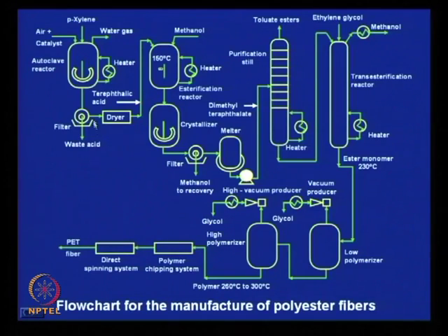So, here this terephthalic acid is manufactured and after it is dried, then it is converted to DMT, dimethyl terephthalate, where this terephthalic acid is fed to this reactor, methanol is added and the temperature is maintained at 150 degrees or so. Like that, DMT is made. So, this is called esterification reactor.